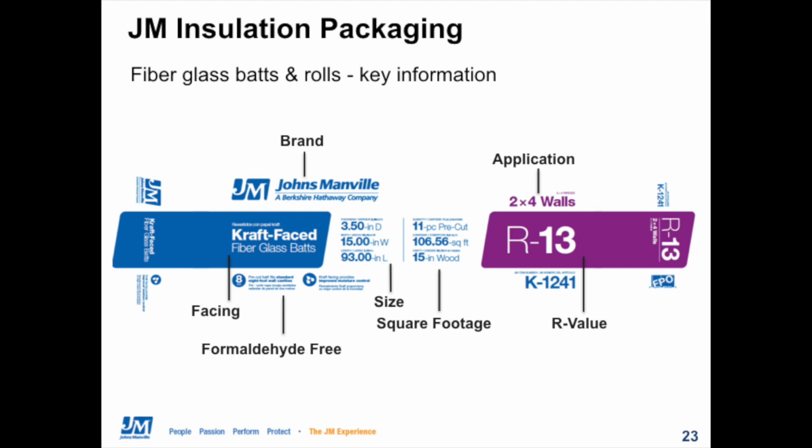It looks like we're on the same theme, but on the foil sheathings, do you need to tape the joints if you have a vapor barrier behind it, such as grade D building paper or Tyvek? That's a great question, and the answer is no. Though we highlighted that you can tape the seams on foam sheathing and then use it as your drainage and air barrier, you don't have to.